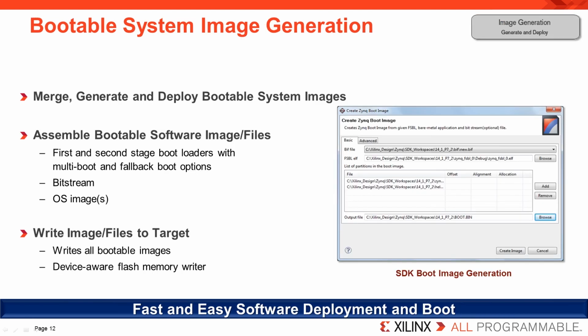As the firmware, hardware, and software development progresses independently, you'll soon need to glue all the pieces together, including the bootloader, bitstream, and the OS images, so that you can move on to full system integration and test. Xilinx SDK includes a bootable system image generator that does exactly this. It collects, formats, and assembles each of these custom elements, and then it manages the write of this data to the Zynq platform using JTAG, network, and more.